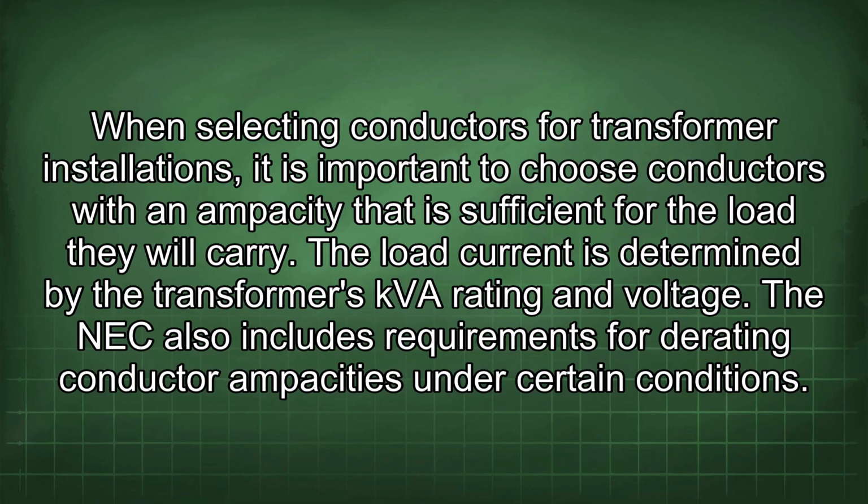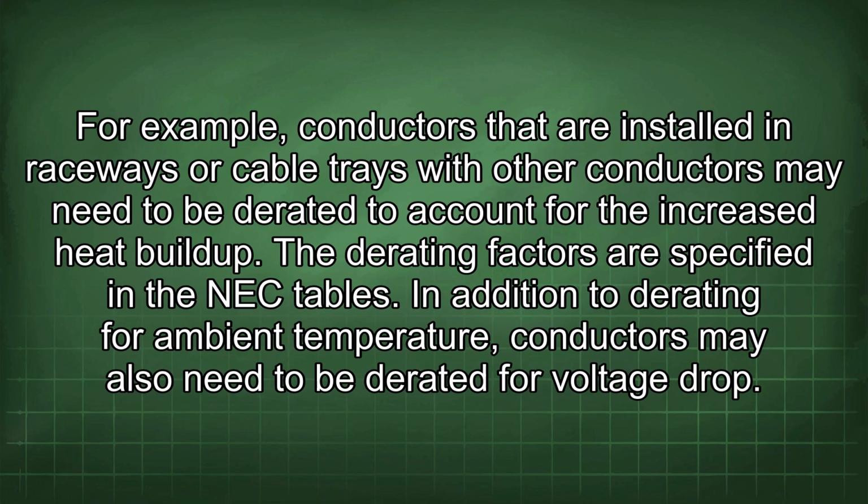The NEC also includes requirements for derating conductor ampacities under certain conditions. For example, conductors that are installed in raceways or cable trays with other conductors may need to be derated to account for the increased heat buildup. The derating factors are specified in the NEC tables.